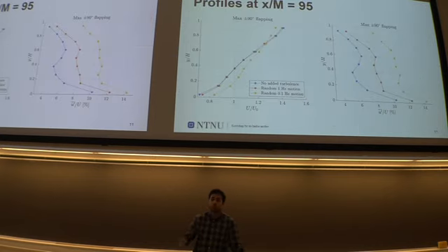These are the profiles further downstream, with a little less data. You can see that, again, they're very linear, and they're well maintained, except for the one with the highest turbulence. That's beginning to even out. Again, I think that's because the higher turbulence mode has more turbulent mixing, and then you even out your flow. And again, the turbulence is not that homogeneous.